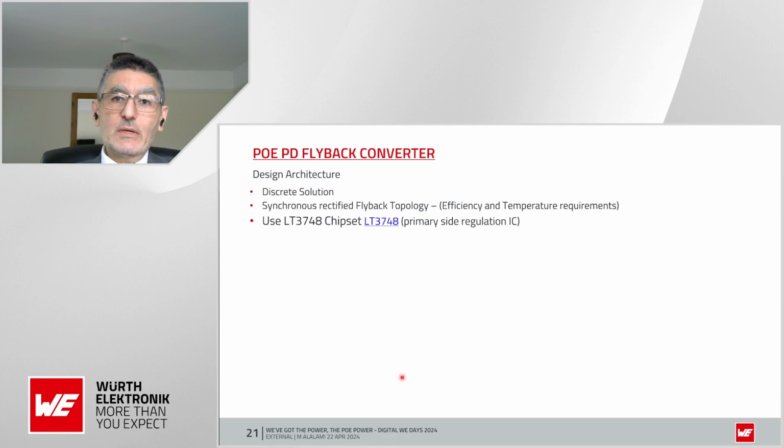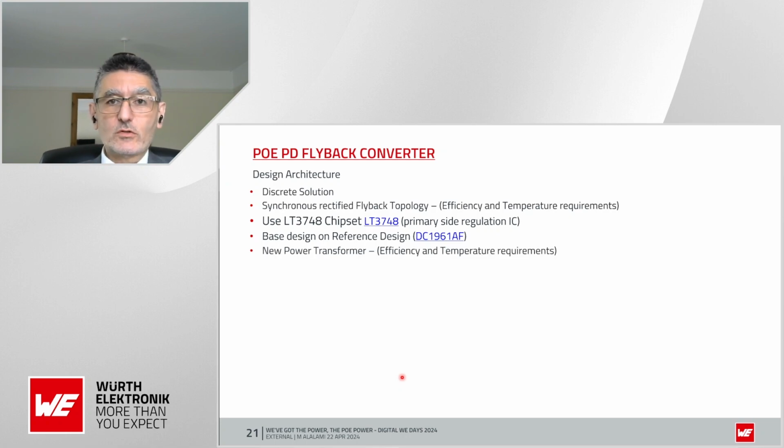This was going to be based on the LT3748 chipset from ADI. This is a primary side controller, and it also has a reference design evaluation board, DC1961. So we have a starting point, or some hardware to use in order to verify the system. We've decided, based on the information that we had, that we needed a new transformer, again, from efficiency and temperature